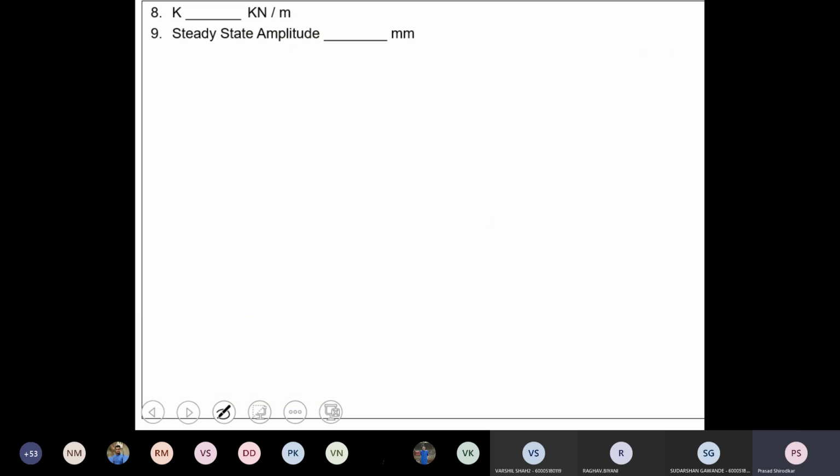All right, and so substitute the value of k in this equation. Any questions? I will just write the equations again on this page for your reference. So here you have to use the equation of R, that is omega by omega n, and omega you know, forcing frequency, omega n is square root of k by m, you know value of m, this is known, given.